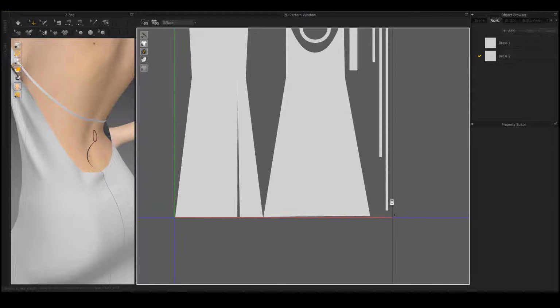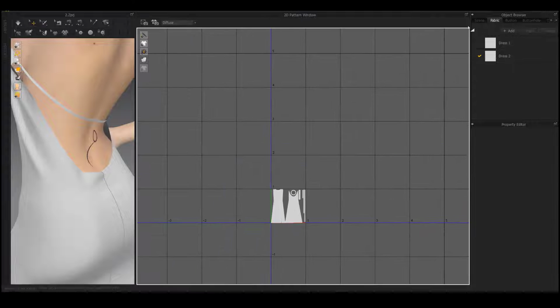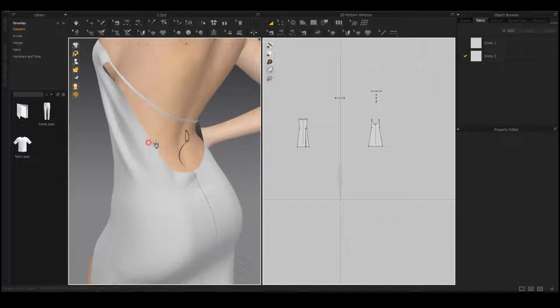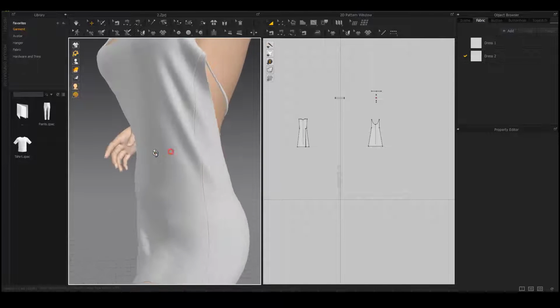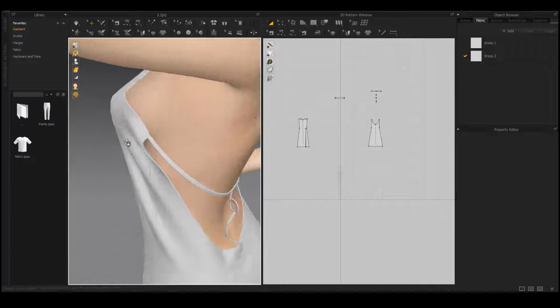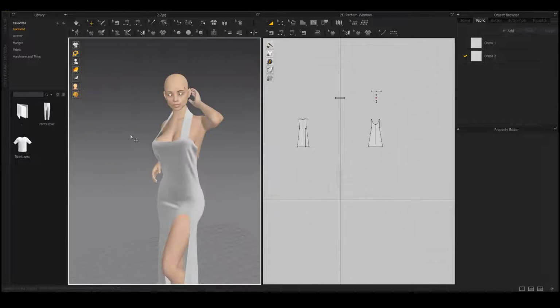The correct topology for other software is quadrilateral, and for the model to be standard, it is better to make the model topology quadrilateral. In the first case, you can select the model and select the quadrangulate option, in the 3D garment section, in the Edit and Context menu. This command allows the irregular topology to become quadrilateral.